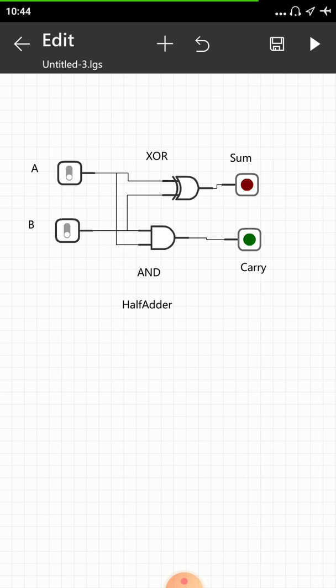Okay, so I have just given you an idea about half adder implementation. You can write the Boolean expression for this from your truth table. So we approach to find an expression through Boolean algebra. We will consider only the ones at output. For that combination of input, we will use the sum of product technique. We will only consider the combination of inputs when the output is high. So the sum of product method we can use to find the Boolean expression.